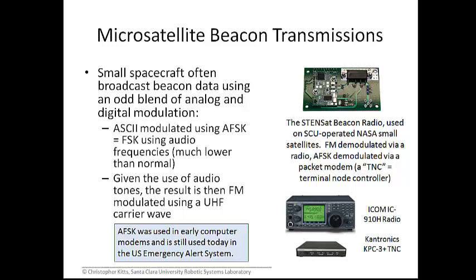You might say, well, why would we do that? And the reason is that there's a heritage of equipment and techniques for doing it this way that comes out of the PC industry with modems. And with modems, what was attempted to do and worked quite well was we took the ones and zeros that we wanted to communicate and we modulated audio frequency waves, much like is happening in the first step here, in order to broadcast them over phone lines.